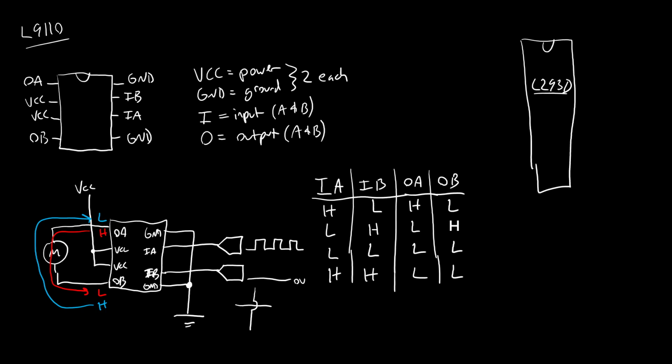Usually these popular H-bridges are fine when it comes to the small motors you would use with an Arduino for building a robot, because they can handle hundreds of milliamps or maybe up to an amp, and that's fine for those small motors. But when you're getting into larger motors, you have to start worrying more about heat dissipation and current limits and heat sinks and all that stuff. But again, not really going to go into that in this video series.